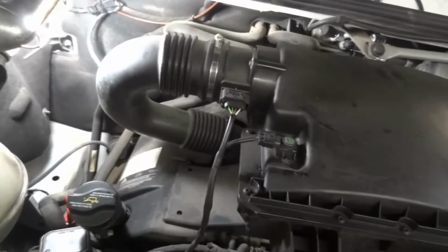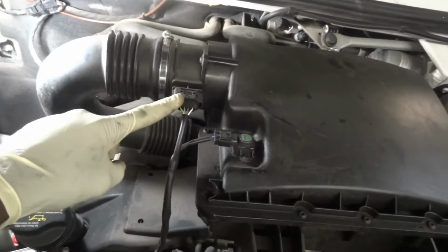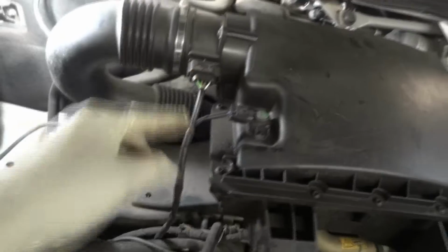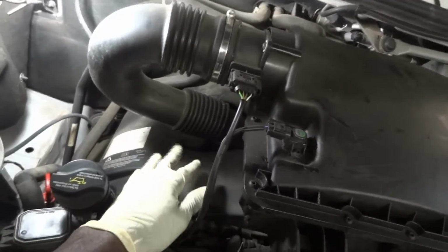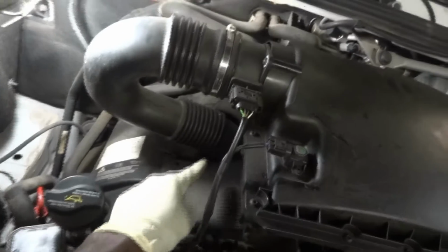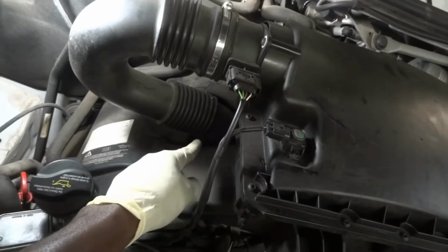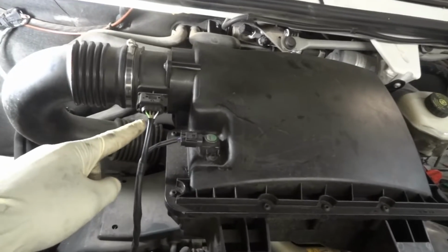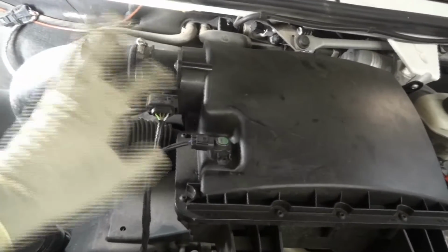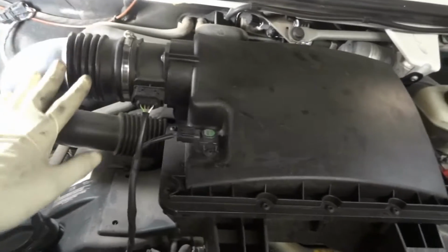So we can check this mass airflow sensor. We can use our lab scope to check this really quickly, or we can take this stuff off and just look at the seal and see if it's out. Maybe that's how it looks, but I'm not sure. I think it's pulled out a little bit. We are probably leaking intake air from the joint. So I'm gonna just double check. This is not really necessary, but it's always good to check and double check yourself.